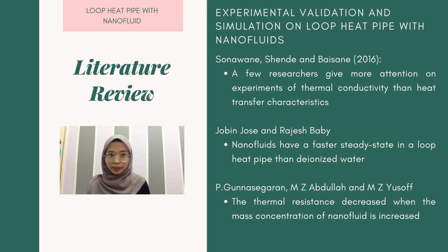So in a previous study, the numerical modeling for a three-dimensional loop heat pipe was developed by Jovin Joss and Rajesh Baby. The simulation was to analyze the effect of silica water nanofluid on thermal performance in loop heat pipes. The result from the simulation proved that the nanofluid can reduce the evaporator temperature compared to using deionized water in loop heat pipes. It is because the nanofluid can enhance the thermal properties through the silica nanoparticles. The experiment indicates that the nanofluid has a faster steady state in the loop heat pipe than deionized water.